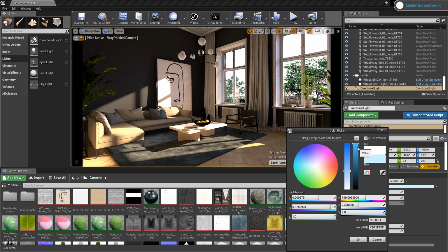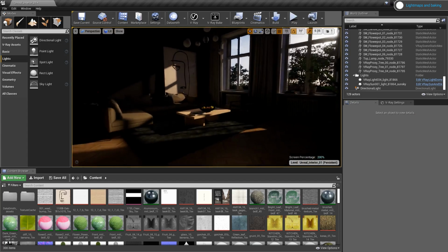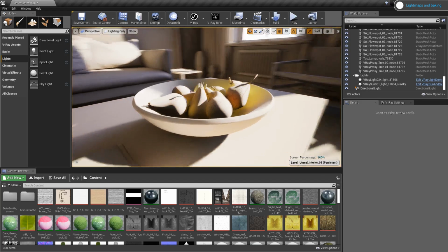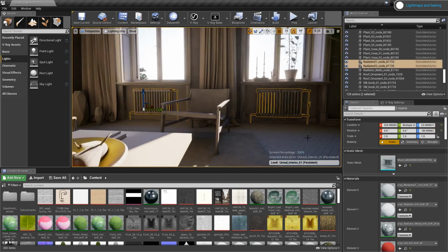Once I'm happy with that, I'll change the light map resolution of some of the objects in my scene, since they can use a little bit of higher light map resolution. Note that once I change the light map size, they will appear dark. This only means that they no longer are using the light map that I've baked using the preview preset.